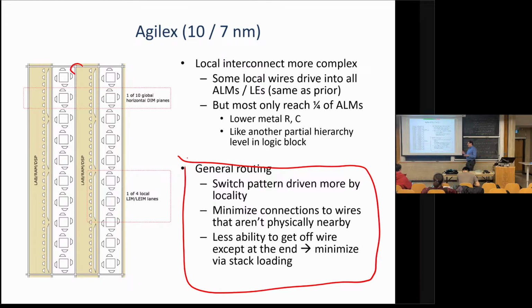So yeah, historically, architecture research in this area, including mine, has mostly focused on, what's the pattern, how many switches, let's estimate how much transistor area. But as your wire resistance is becoming a bigger deal, and capacitance has always been a big deal, but it's becoming an even bigger deal, you really want to have a switch pattern that keeps all the internals of those muxes small, right?